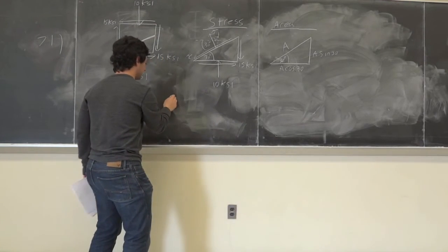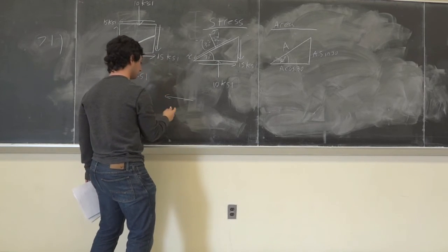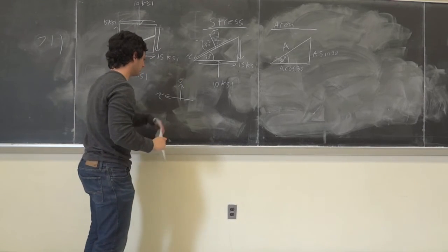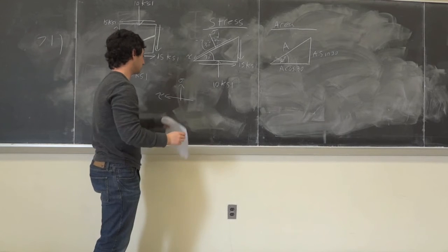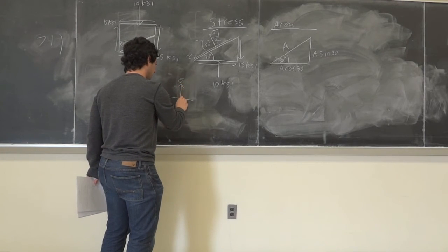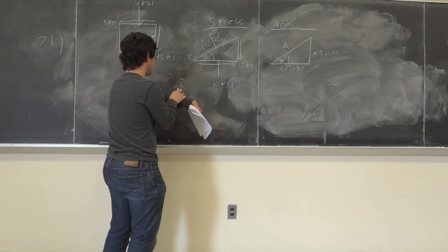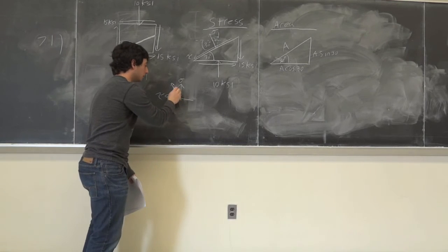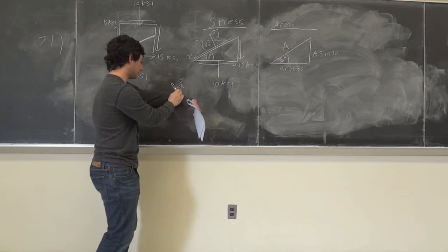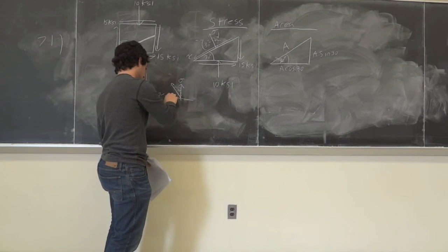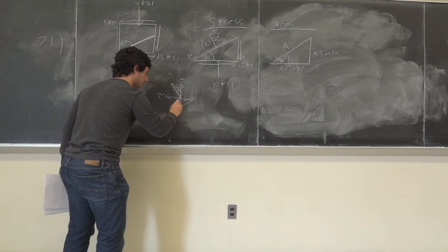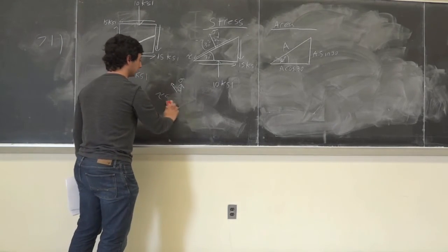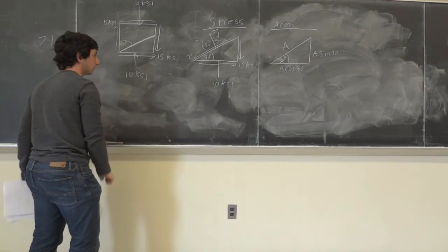What I'm saying is, let's think of tau being just horizontal, and then sigma being straight up. Now we're tilting it 30 degrees. So originally it starts over here, and when you tilt it, it's going to end up over here. So now sigma's over here. This angle's 30, and this is going to be declined now. So now tau's like this. So this angle has to be 30 as well. You guys follow? Because you need that to do the force balance.